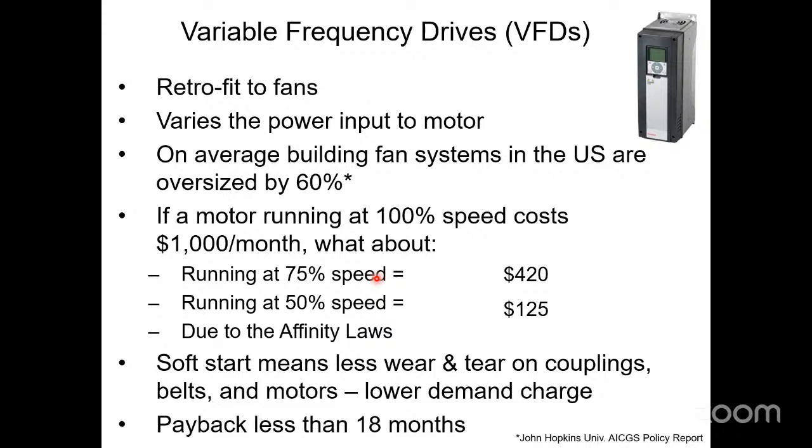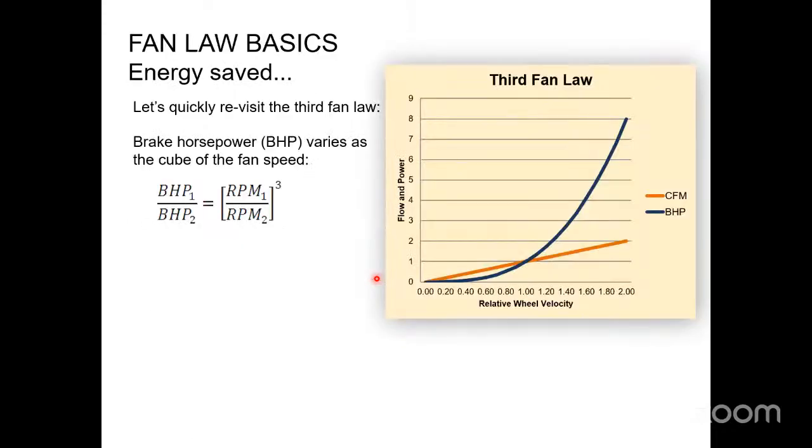Paybacks in general on VFDs are actually pretty good. VFD costs have gone down and electric prices have gone up over the years. So paying back a VFD is a pretty attractive upgrade if somebody wants to abandon the inlet guide vanes on their old air handler, if they still even have that thing, and upgrade it to a VFD. This is why a VFD will save you money, if you will.